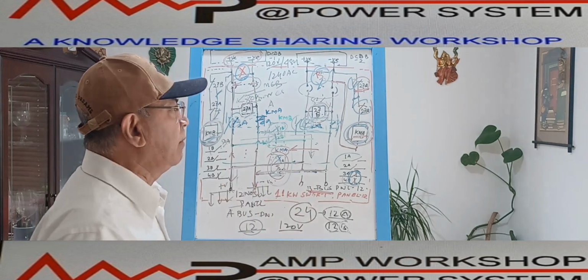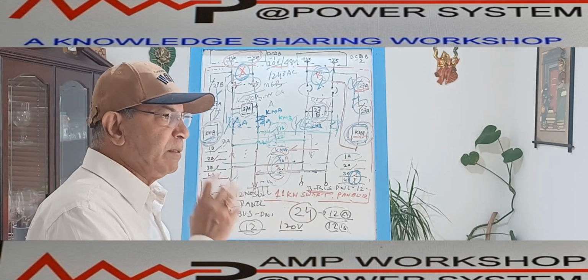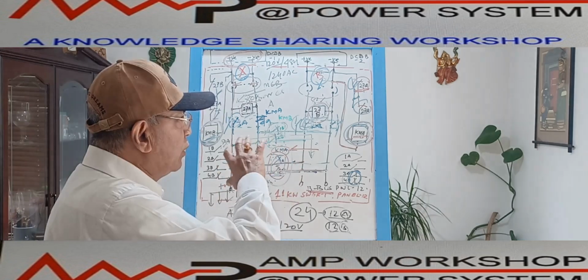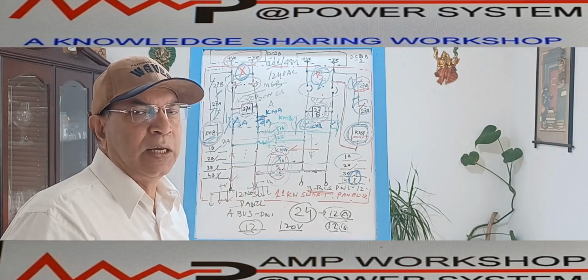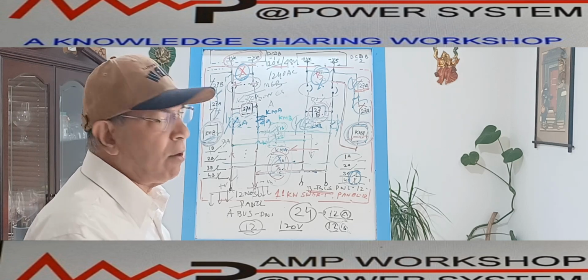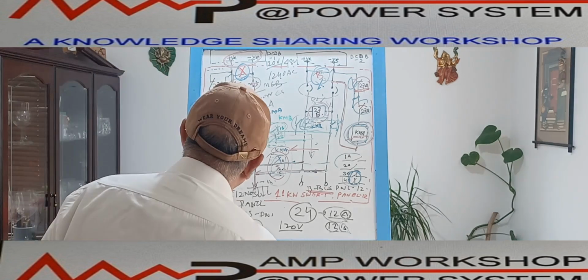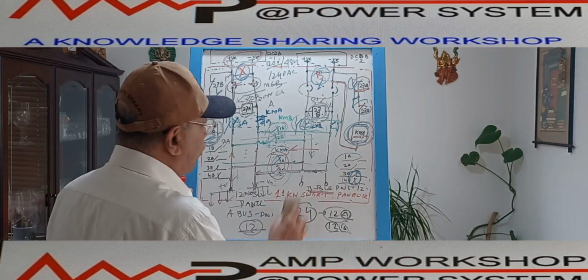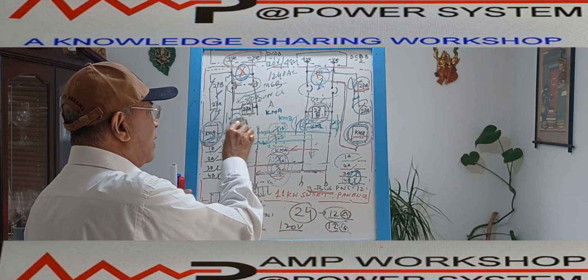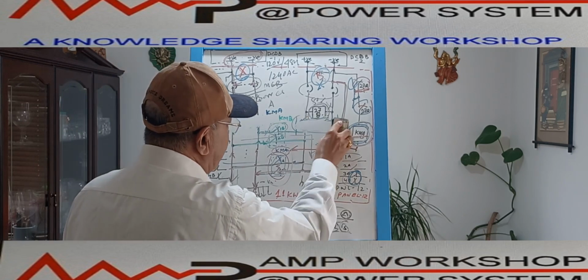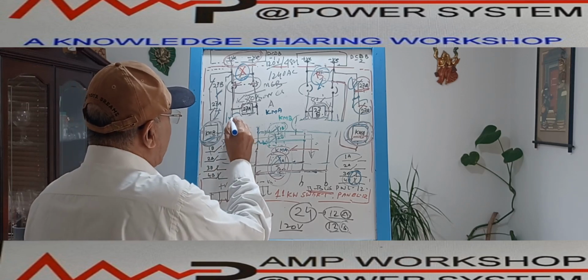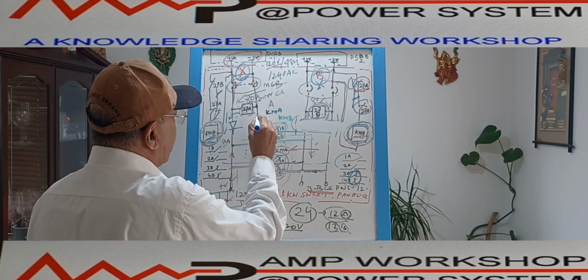In case of DC supply, if we feel that this power supply changeover time of some milliseconds is not acceptable, and we need a continuous power supply without any interruption, then we can make an alternative arrangement. And second point, sometimes we do not have a 4-pole contactor. In case of DC supply, we can make another arrangement. Instead of the NC contact, we can use a diode over here. Okay, we can use one forward bias diode over here, one reverse bias diode over here.